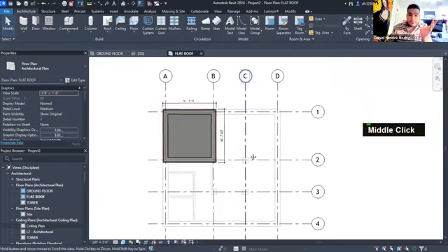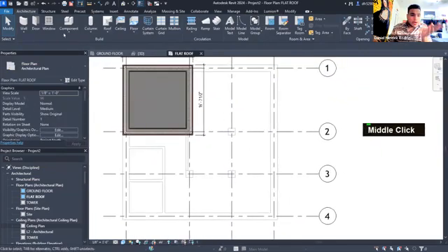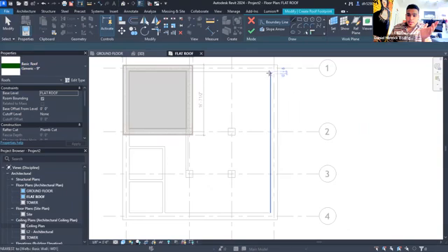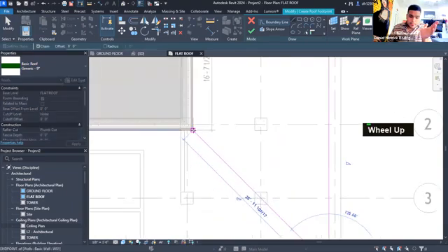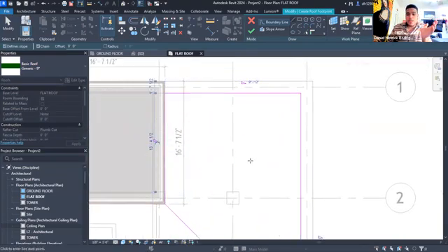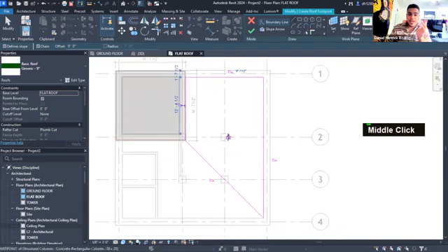We're making a flat roof, and to those of you who didn't know this, flat roofs are not flat because you can't have water pooling on top of a building. That's extra weight, and that's risking water getting into the building. So every roof is sloped. Flat roofs just happen to have a very, very small slope that you can't really notice when you're walking on it, but it is there, and water will run off of it.